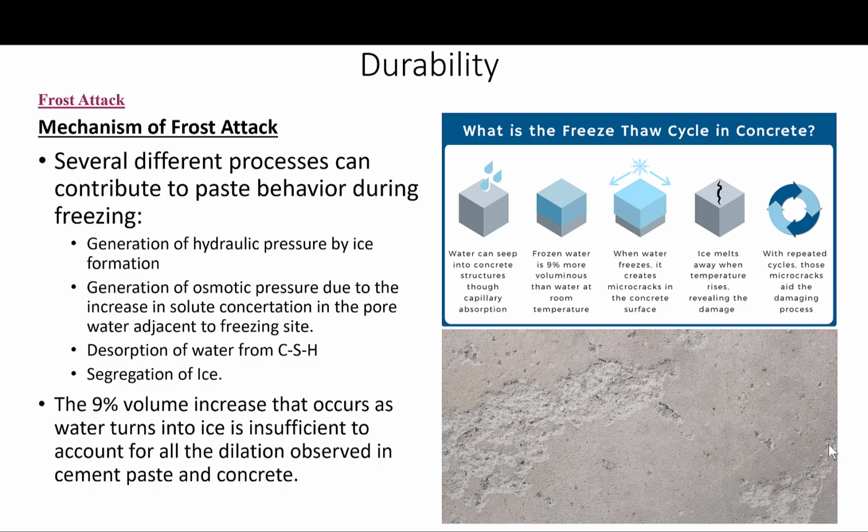So both osmotic pressure and the differential in vapor pressure have a similar effect. So these are the explanations besides the hydraulic pressure. Also, the buildup of ice in particular parts of a structure on a macro scale may aggravate frost damage in concrete, although it is not the basic cause.